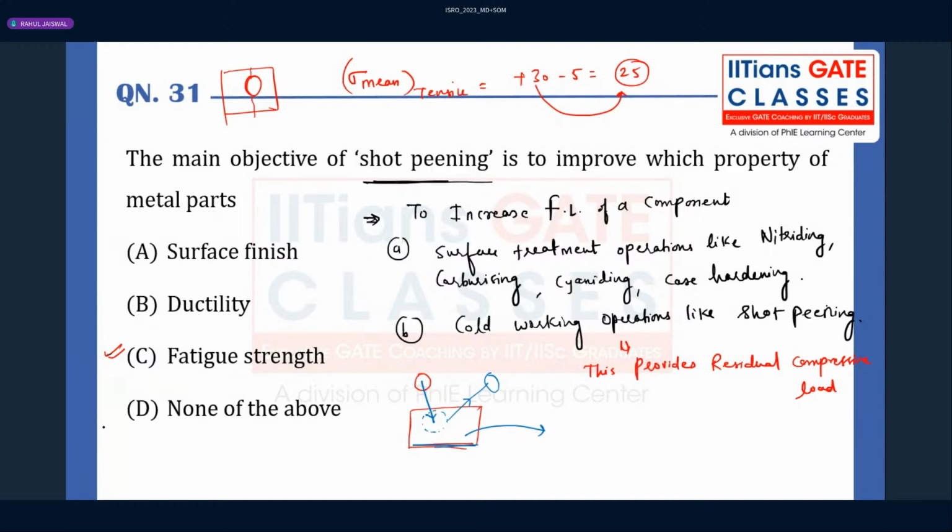So in those circumstances, we have to do some operations so that we intentionally try to introduce compressive stress, because you know that the compressive stress will not cause anything on the endurance strength of a component, right? Even though you keep on applying the mean compressive stress, the endurance strength is constant. This is the horizontal line. Whereas you see mean tensile stress, because of this, it is subjected to decreasing endurance strength.